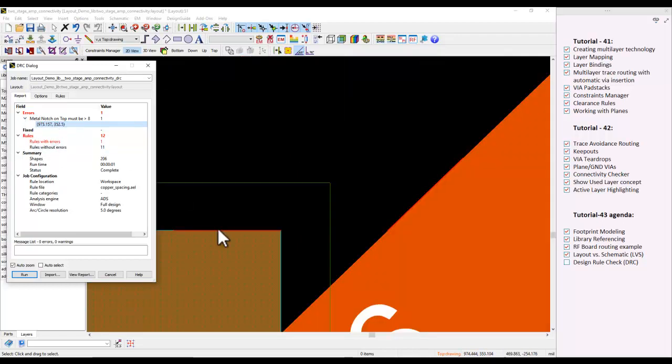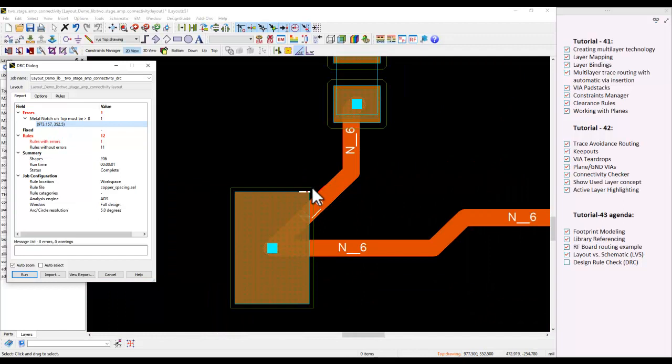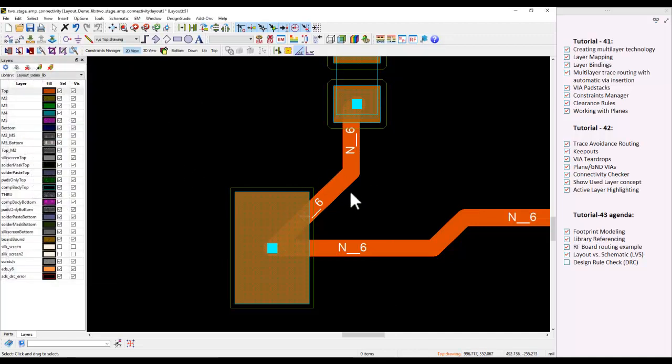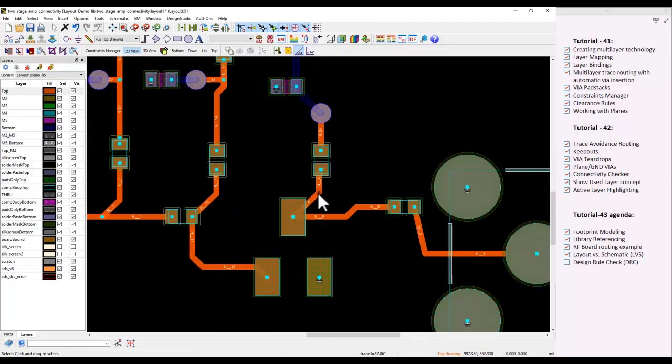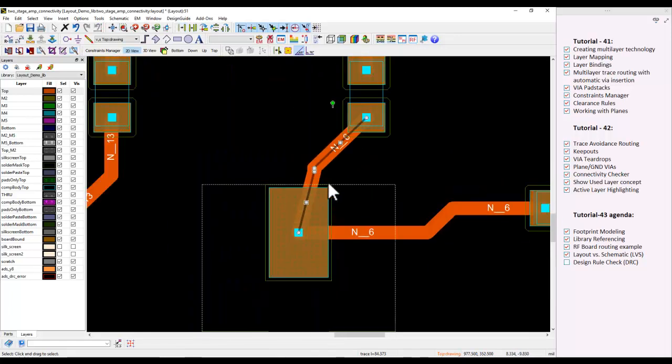Now the other issue is about this via handling. It is saying this edge is at an angle, which should be greater than 8, but it's not greater than 8. So now we can click on this trace, and I can edit this trace information, or I can reroute this trace. For example, I can make this trace be routed something like this, or I can just delete this trace and create a new trace.